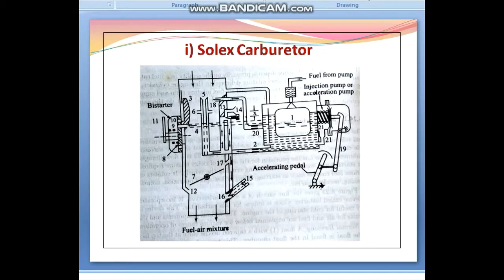These holes connect the starter gasoline jet, that is number 9, and the starter air jet to the passage, which opens a hole just below the throttle valve, that is number 10. Smaller or bigger size holes come opposite the passage depending upon the position of the starter lever, that is number 11. The starter lever is operated by a flexible cable from the dashboard control.